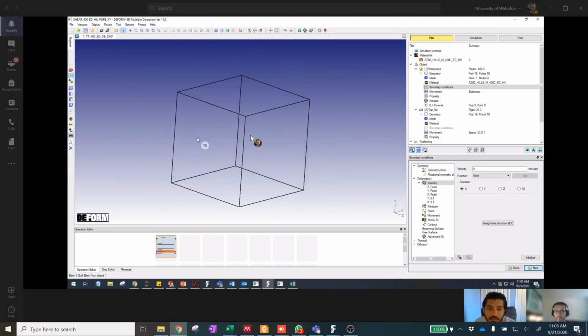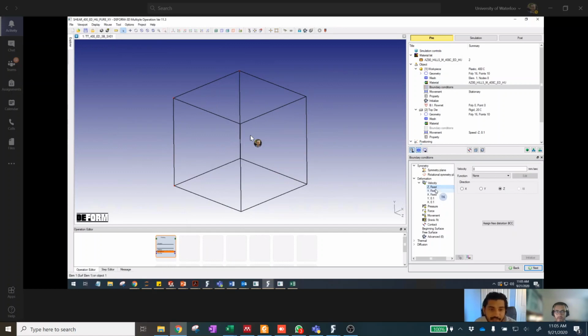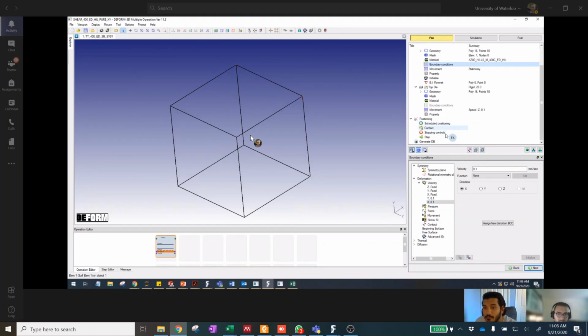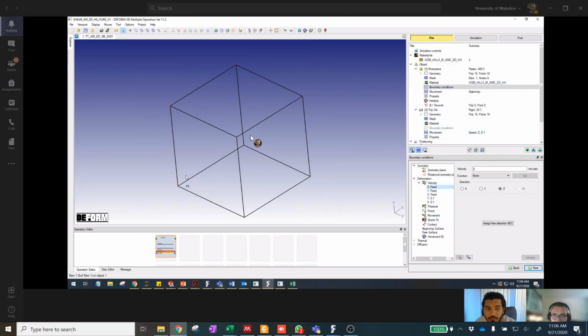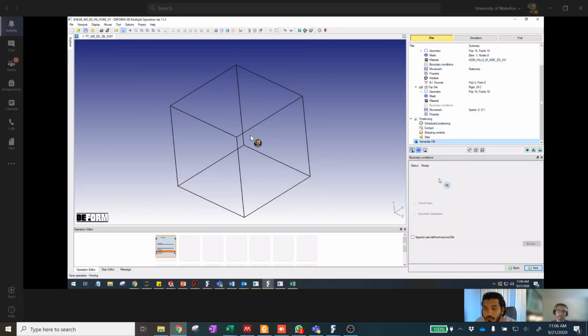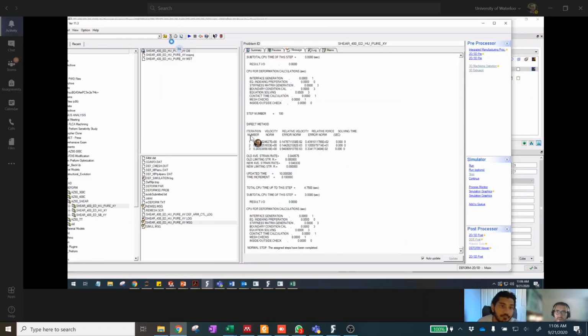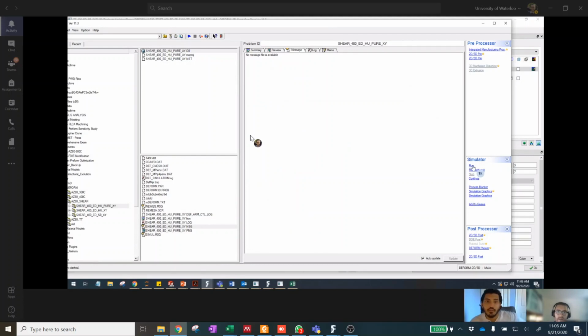That's what I'm finding. I didn't think this would take me this long. Right now we have this face constrained, Y down here constrained, X constrained here, and then positive Y, positive X displacement. That's fine. So go to the Z again. Which nodes are constrained in Z? One whole face, yep, perfect. Okay, run that. Hopefully it doesn't crash. I don't think this is going to crash because we have that other face unconstrained.